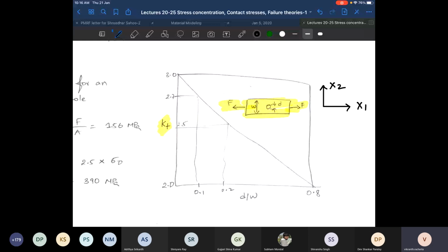So at the critical location B, which stress is high, sigma 1 1 or sigma 1 2, in the in-plane stresses? It would be sigma 1 1, which is high. So the stress concentration factor you are interested in is Kt. Now what is Kt depending on? What are the relevant geometric parameters in this problem? The width and the diameter, yes, the diameter and the width.